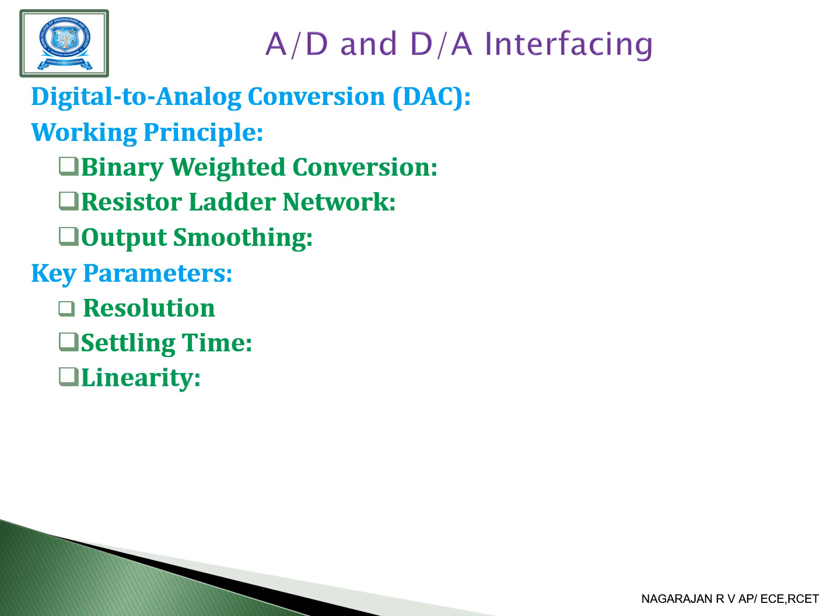Next, linearity. The degree to which the output analog signal is proportional to the input digital code. So non-linearity can introduce distortion in the output signal. Next one is output range. The range of voltage that the DAC can produce. Some DACs provide a rail to rail output, covering the entire supply voltage range.